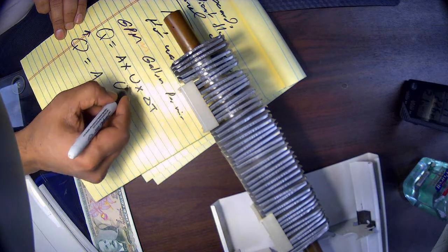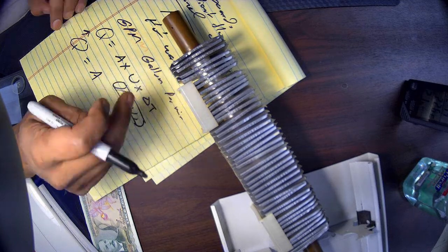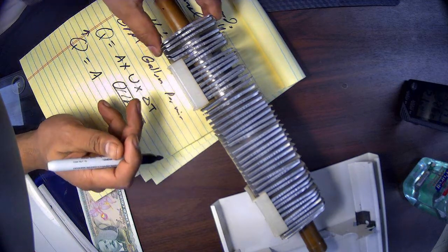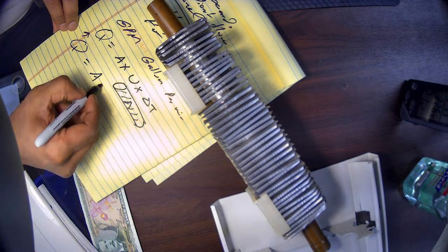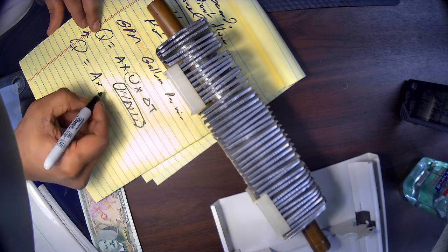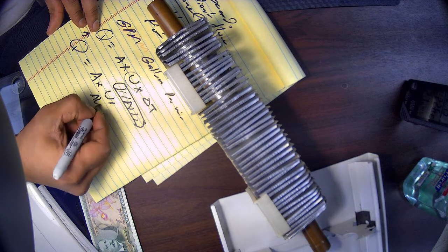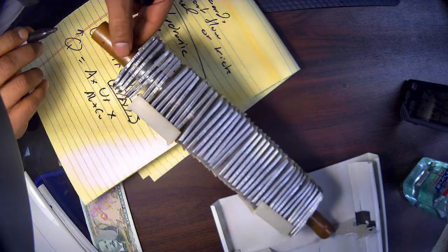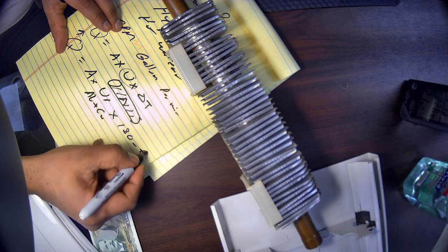The area of this pipe is the area of this tube over here plus the area of each one of those squares, the little fins, because they are connected with each other. This is going to be my area, times U, which is the material, aluminum and copper, which are the best conductive materials. So that's the material U over here, aluminum plus copper. And delta T here is going to be the temperature difference between the water inside and the room. So that's going to be 180 minus 65.